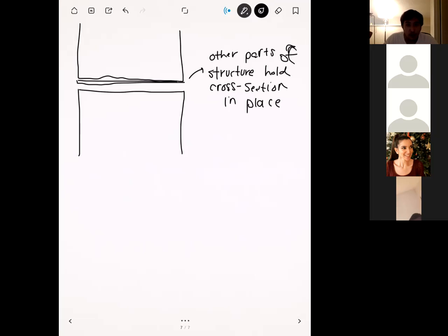Right. So that's plane stress and plane strain, and so be on the lookout for those cases, because if you can run a 2D simulation, that's always going to be way faster than a 3D one. Okay. For cases where you can do that, it really saves you a lot. For your projects, I don't anticipate too many of you being able to do that, but it's good to know in general for after this class.